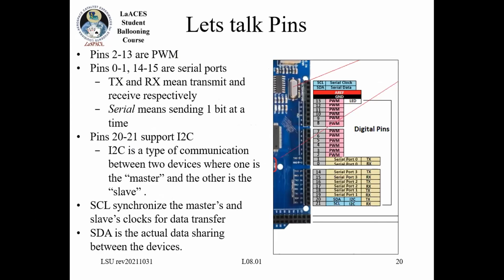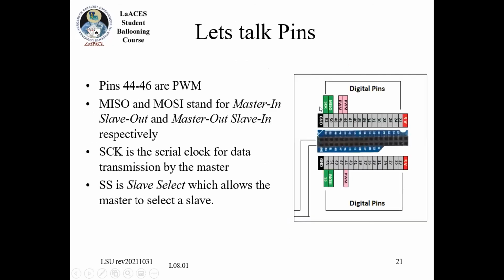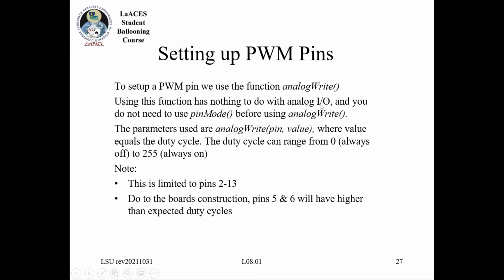So like I said, if we go back to our pin diagram, you're limited to these ones that actually have the hardware PWM functions, pins 2 through 13. And then just as a quick caveat, apparently pins 5 and 6 are going to be slightly higher duty cycle than you would expect. So that's something to be aware of if you were looking to use those two specific pins. But that's it. So that is it for the lecture for today.